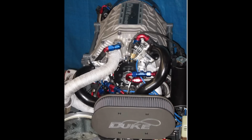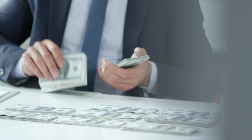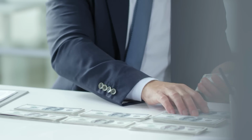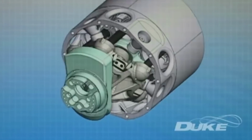But the amount of development, testing, and progress is far inferior to the traditional systems. For instance, a 1000cc 4-cylinder inline engine from a superbike produces 180 to 190 horsepower to the crank, where the same capacity axial motor only produces 125 horsepower. And that's not where it stops. Because there is much less resources invested in them, it will most likely have some teething problems, like failing joints, and with a sliding head, I think the longevity of the head gasket is a genuine cause for concern.